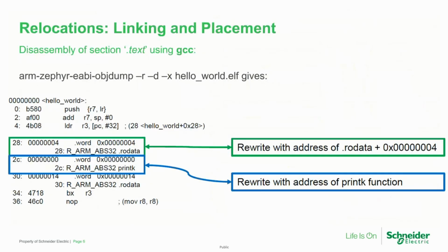So I was talking about relocation and about the address. As I said, when you want to call printk, when you do some partial link with your new ELF file for LLEXT, the address of printk is not there, so you have to parse it. So basically, you parse the firmware here. You see that the address is basically 0 plus an offset of 4, and so you have to find this code, and then you patch it. You have to add some ARM parsing code to catch it, modify it, and then you are able to use it.